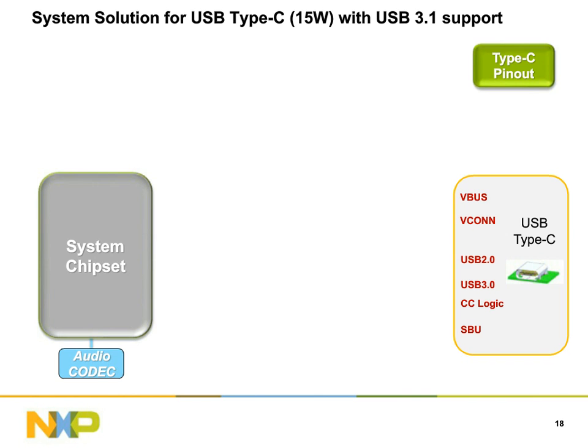I'm not going to talk to any video devices downstream, so I don't need alternate mode, I don't need power delivery. I'm happy with 15 watts, and I would still like to use the USB 3.1 channels, the high-speed channels. So how would my system design change? And this shows how scalable the Type-C design is. So let's look at this system very quickly.